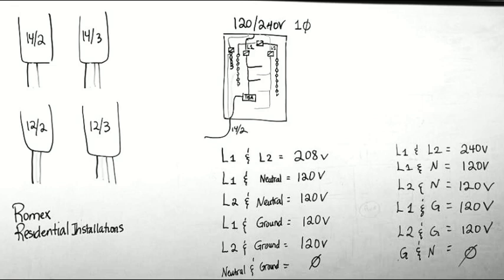So they make them stranded, which is very flexible to maneuver, and it's easier on your hands as well. So this is an 8-gauge wire, and this one has a 40 amp capacity, right? And we can go on with larger and larger conductors.